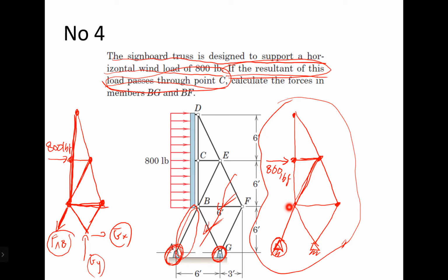You cannot do it that way, William, because with one cut like this, three members, the unknowns will be there, but the other unknowns, what is happening at A and what is happening at G, you haven't solved yet. So you can do the cutting, but after you solve for the external forces. You get it? Yes, I get it, sir.